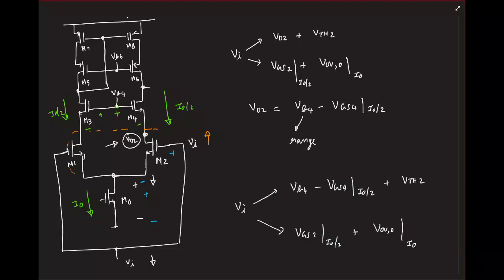And by the way, just one fine point. The ranges we compute, if you see how we are doing for the input, at the input we are assuming both the inputs are increasing or decreasing together, right? So it is the common mode for the input. This is the common signal that you can apply to the inputs, making sure all of them are in saturation.